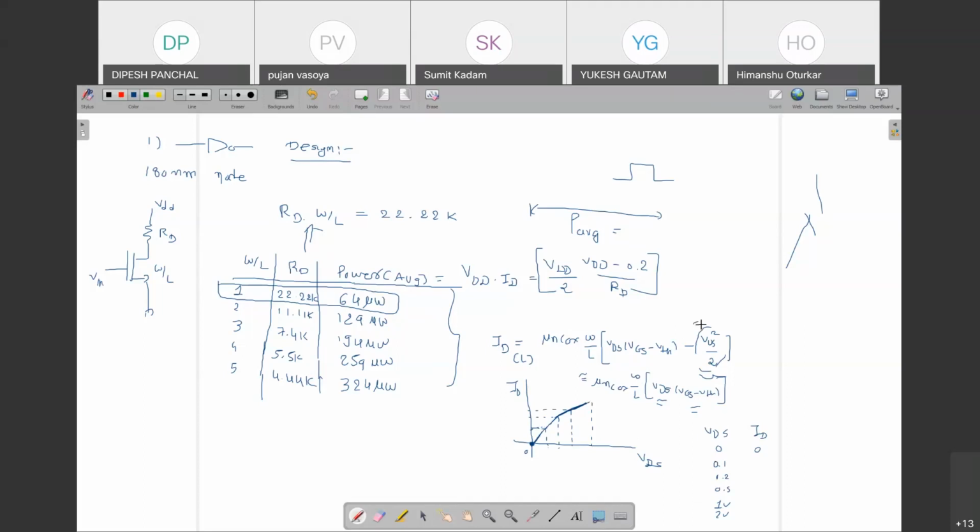You have to consider this term, 4 square by 2, let's say 16 by 2, 8. You cannot neglect it as compared to the first term. So non-linearity starts and the graph looks non-linear. Once you take higher and higher values of VDS, non-linearity is introduced and the graph becomes non-linear. So if I want to use this device fully on, behaving as a small resistor, which value of VDS do I have to take? Very large or very small?